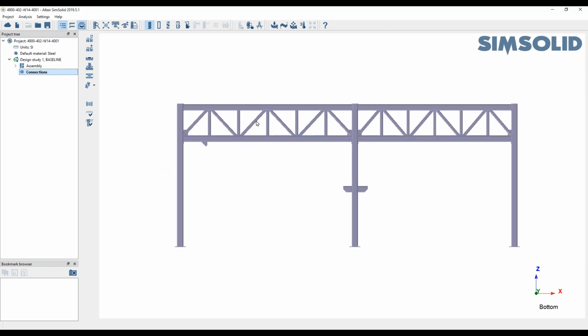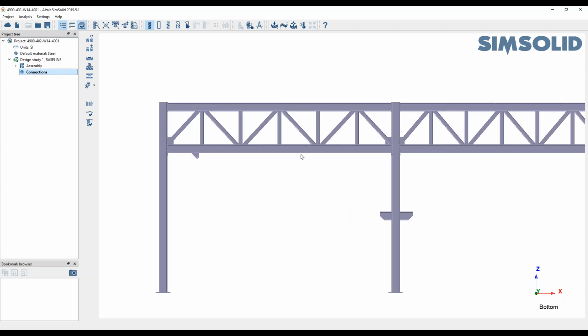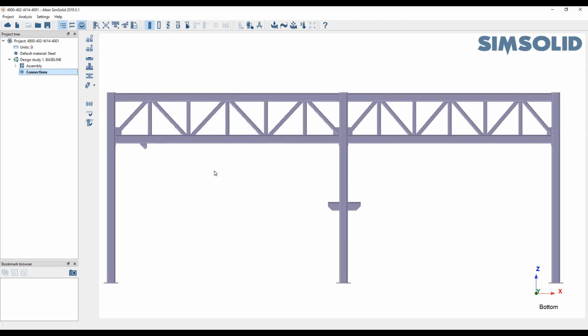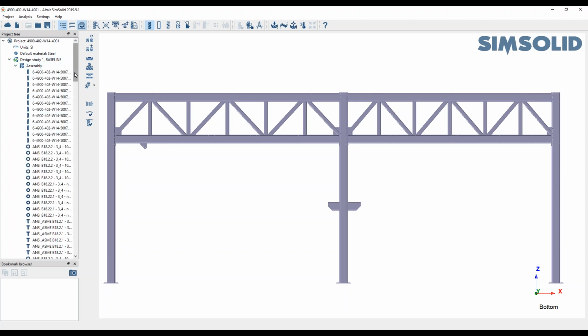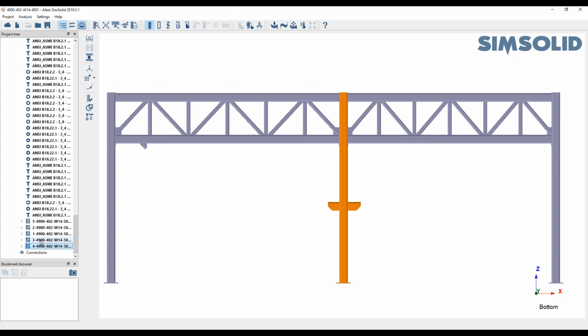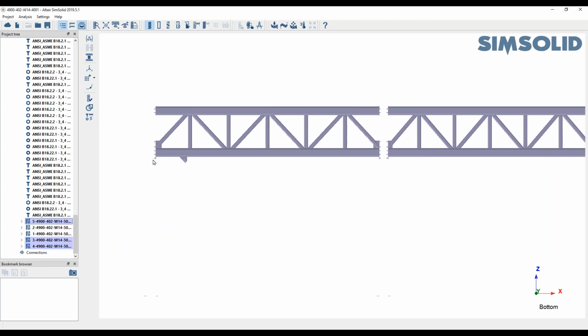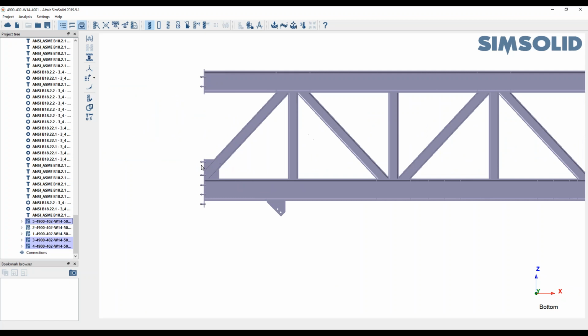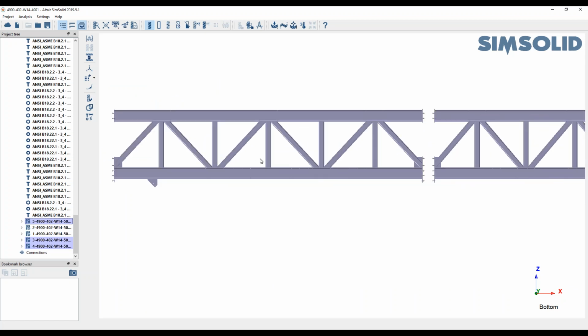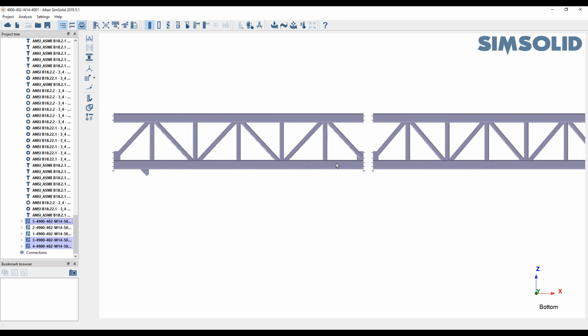Now, basically, the horizontal sections or the frames are all welded. So what we're going to do is isolate everything else and then create welds between this structure and this structure here. There are numerous ways we can do this. So we can go into here, and there are my sub-assemblies. The ones I'm going to pick are the vertical ones, and let's hide the selected parts. So I have got the bolted connections, but it's not going to weld the bolted connections and the holes because we're going to set a tolerance for my welds for a minimum size. So let's zoom out again.